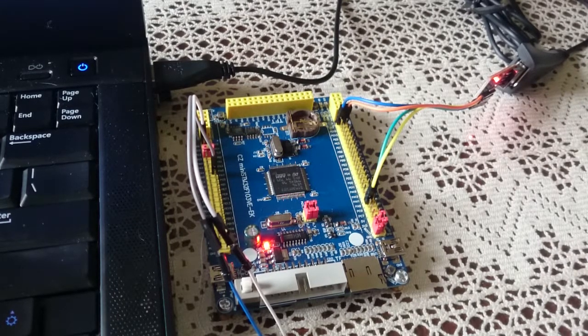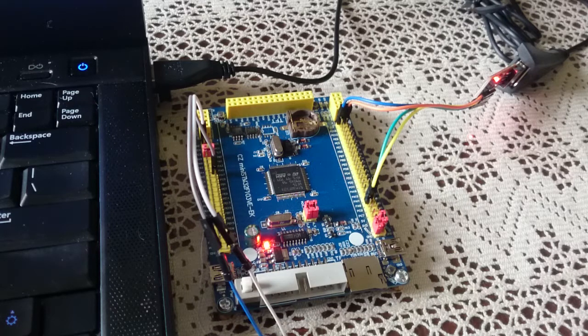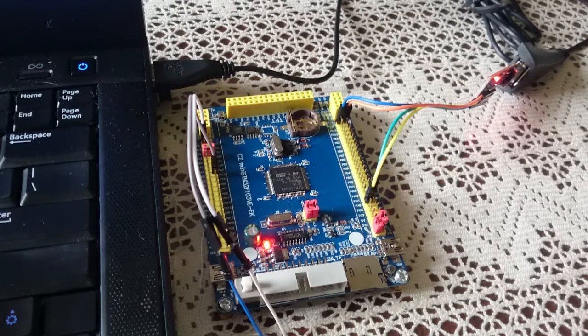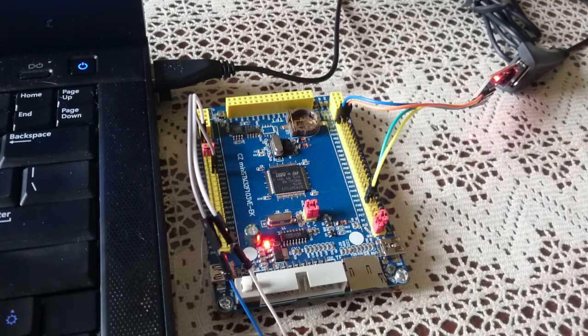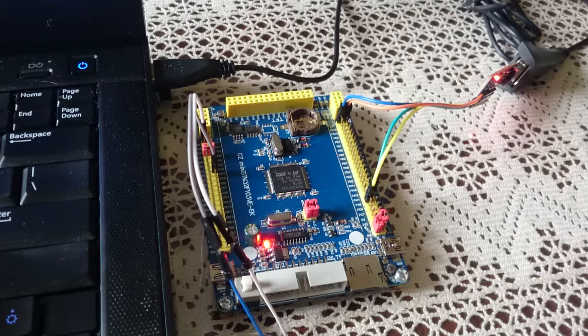Okay, so this is the CZ Mini STM32 F104 VE board, and it's a 72 megahertz board, and it has lots of pins. What we need to make it work is a dedicated chip for the EEPROM, because its internal EEPROM is, first of all, small, 512 bytes, which may be okay for everything except the periodic error correction, but it also uses a different API because the smaller ones assume integers and things like that, 8-bit space rather than 16-bit, which can be bigger. So I have an RTC adapter module which has an EEPROM on it, and hopefully that would work.